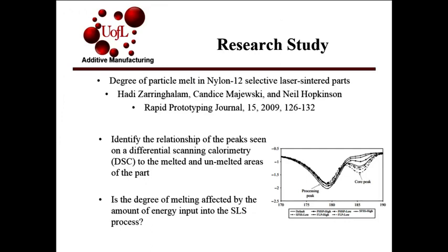Parts. The authors and the journal are listed below, and the scope of this paper was to identify the relationship of the peaks seen on a differential scanning calorimetry, or DSC, to the melted or unmelted areas of the part. One of these DSC charts from the experiment is shown to the right. The key question addressed was, is the degree of melting affected by the amount of energy input to the SLS process?